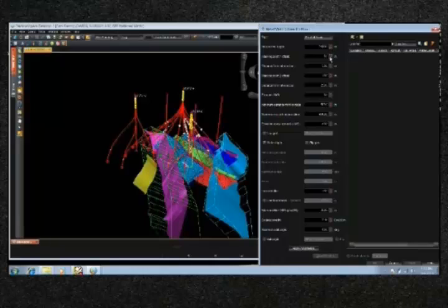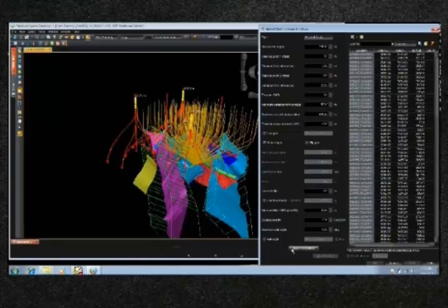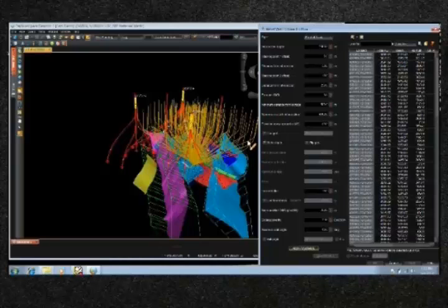and from within this dialog we then key in the parameters as required. The input parameters have been organized in such a way as to reflect a typical relief well plan process, where we begin with the intersection depth and we work our way gradually upwards to the various tracking point offsets as well as the distance from those intersections. Once these parameters have been specified, we then hit apply, and the application now cycles through those values as well as considers the need to avoid intersection with those faults. It then generates a list of relief well plan options for us.